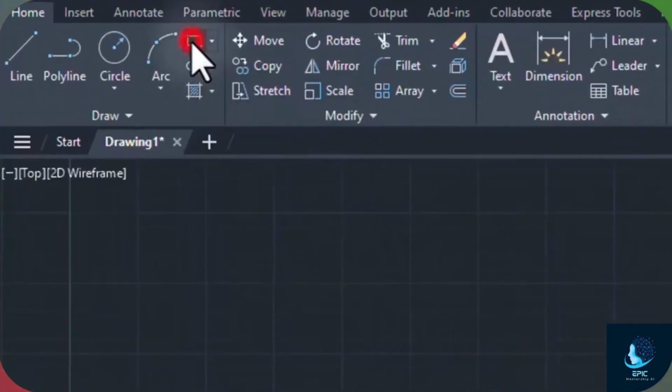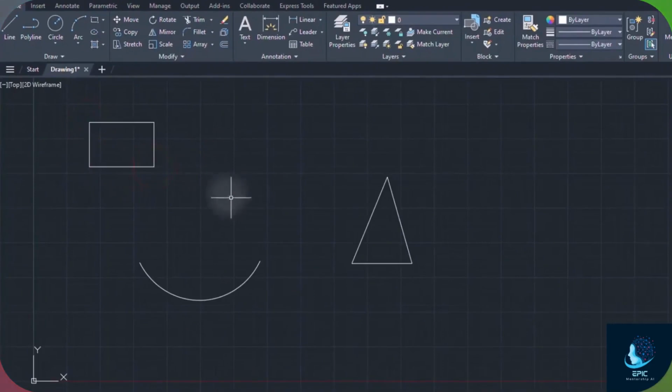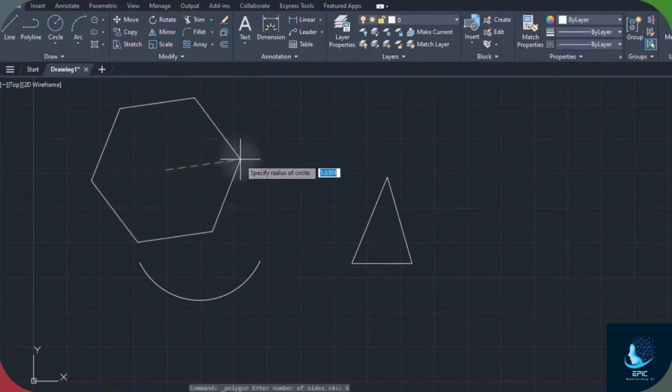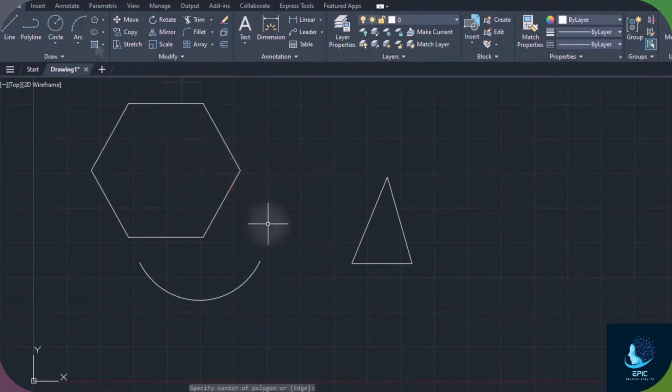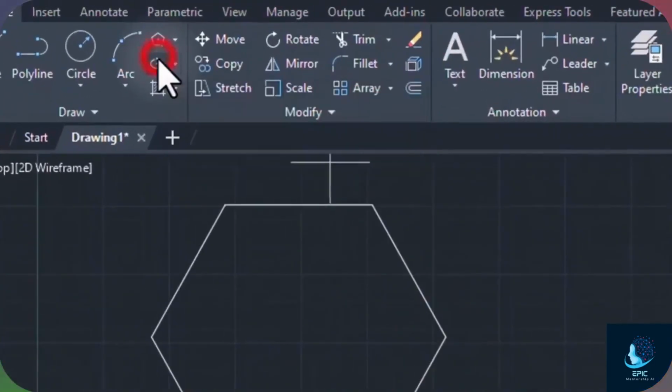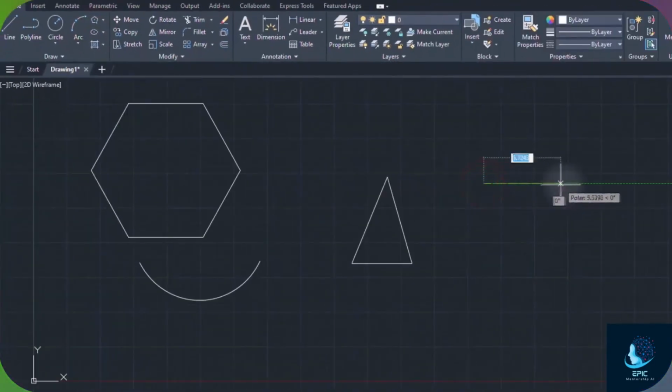Use the Rectangle or the Polygon tool to draw these shapes. Type the number of sides, apply with the Enter key, and fix 2 points to drop the shape. Enable the Ellipse tool to drop an ellipse with 3 points.